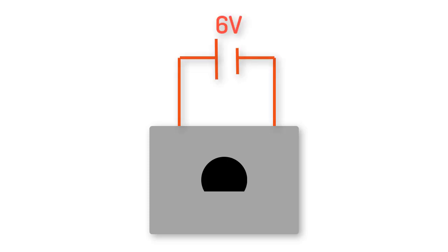First, motor speed is linearly related to the voltage that you give the motor. For example, suppose I have a motor sitting on my desk and the motor shaft isn't attached to anything. When I connect the two terminals of the motor to a 6-volt battery, the motor will spin at some particular speed. If I now disconnect the battery and connect the motor instead to a 12-volt battery, the motor will spin twice as fast. Since I doubled the voltage, the speed will double also.